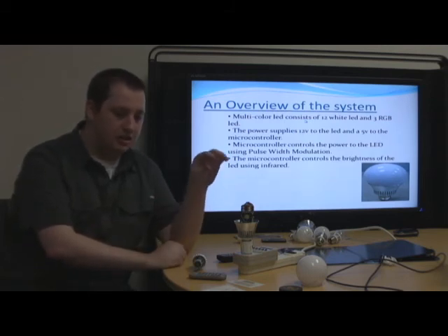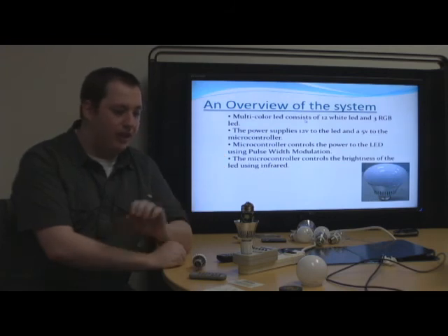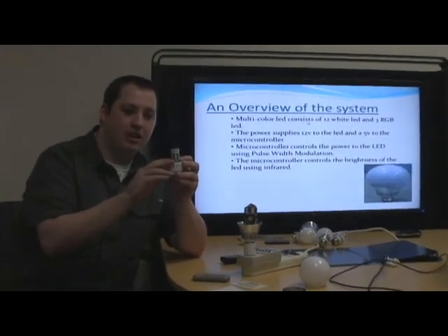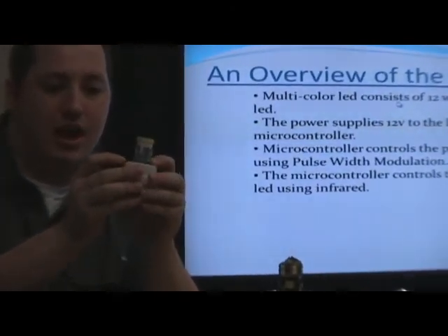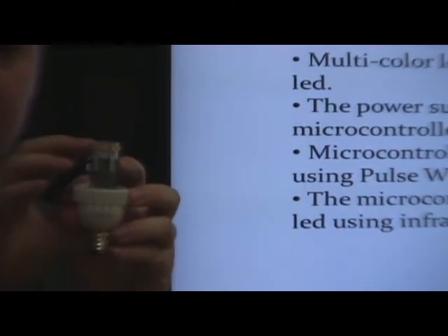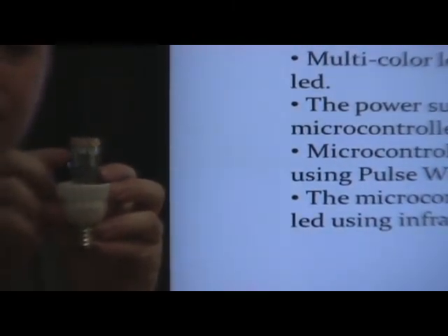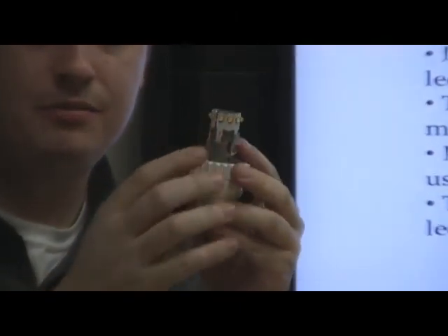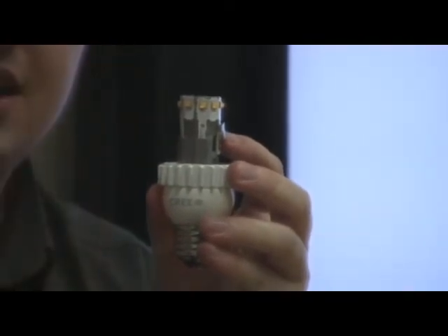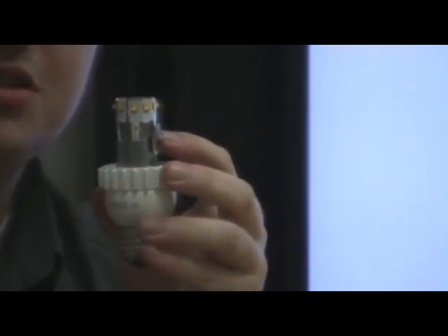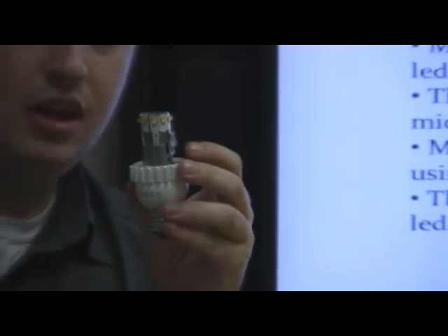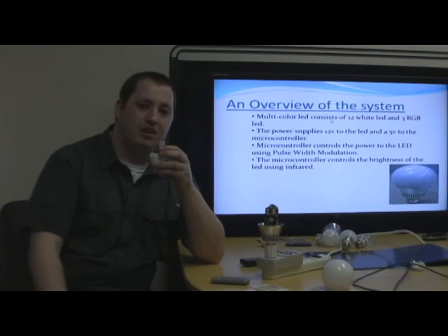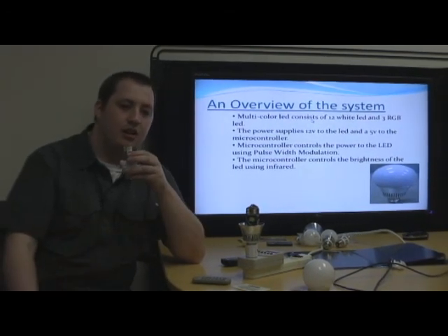The second issue was there's still a slight heat issue, and for that we could solve that using technology like these in the newer light bulbs that are out. What they use is they mount the LEDs themselves on actual metal that has traces marked on it with an insulated coating. This dissipates the heat much more efficiently than the PCB boards that we use on our design. And as you can see, they also use a large metal heatsink. And for ours, we could also mount a larger metal heatsink on there to pull more of the heat away from the LEDs.